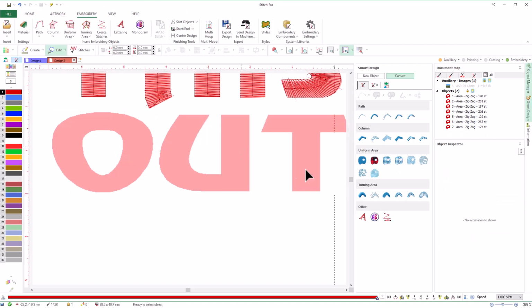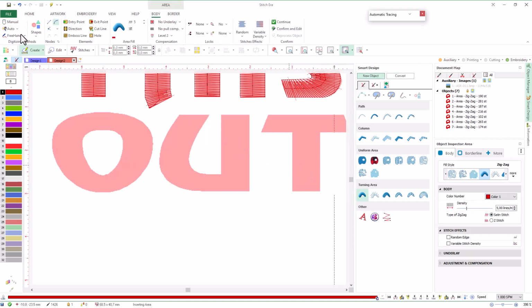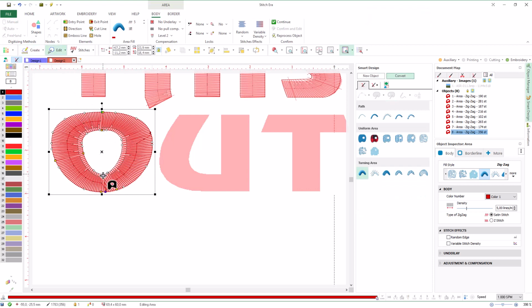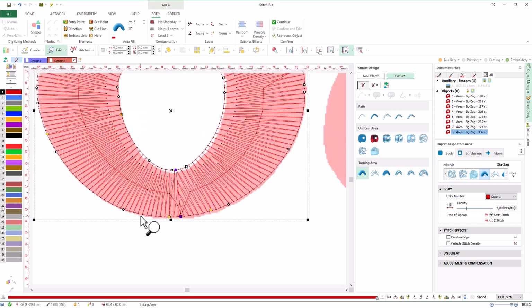Select turning area with zigzag and auto-complete. Click to capture. As we can see, unlike auto trace, auto-complete captures all the contours of the region, and not just one of them. Select Accept in the context menu and check the object. Auto-complete added a cut line and direction lines, as expected. However, it added direction lines at each side of the cut line to get a result similar to the cut line and direction combination we used before.